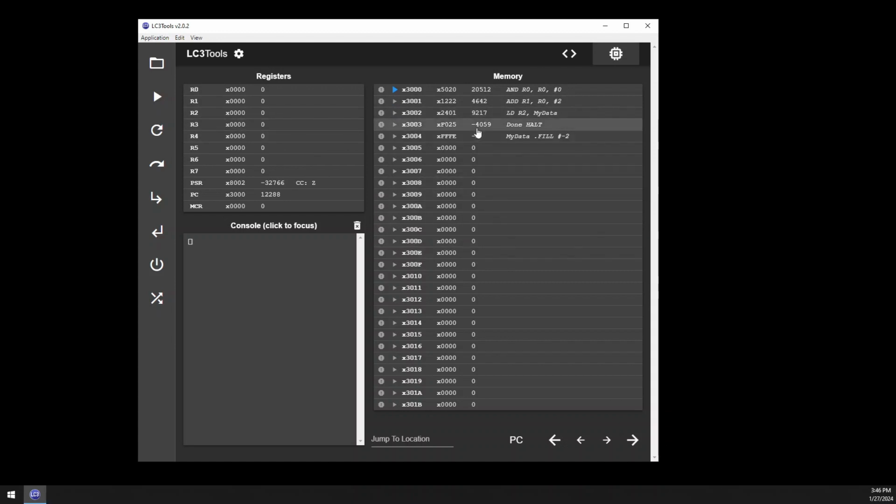And of course, as you execute or step over each instruction, you can see we're here about to execute this instruction. Well, that instruction didn't really change anything. It just made sure that this was a 0. Now we're going to add 2 to whatever's in R0, which is 0. Store that in R1. So we'll see R1 change now to a 2. Okay, so now there's a 2 in R1. So as you step through each of your instructions, you can see the results here in the registers.